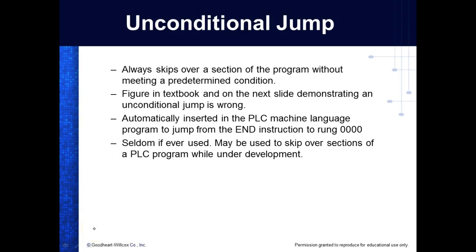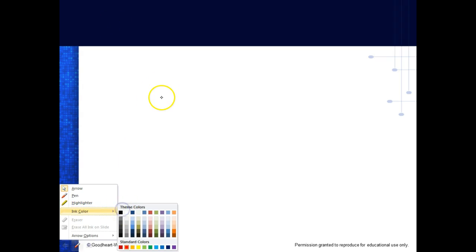So I'm up here writing ladder logic. So the jump is to, I need to not include the numbers of the block. I'm going to come up here and just show you that. So I'm going to say, okay, this is a rung, this is a rung, this is a rung, this is a rung. And down here I put a jump. And then I say, where do we want to go? Well, I want to go to here.